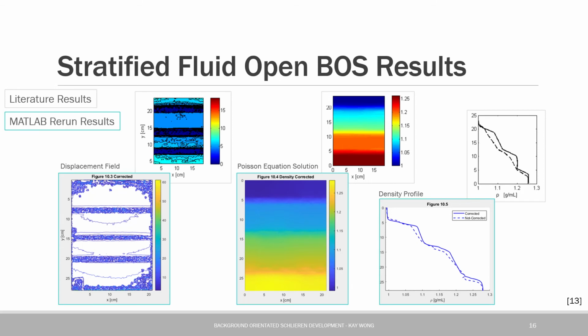This software has provided a solid insight into the possibilities of the project, where it is evident that the displacement field calculation using cross-correlation is refined, but the refractive index solution using a discretized Poisson equation is less developed and more prone to errors. There is also a large number of setup parameters, which are difficult to locate and change. My software solution should improve on their approach to Poisson's equation and have an easy-to-understand image processing interface that can process a variety of images.